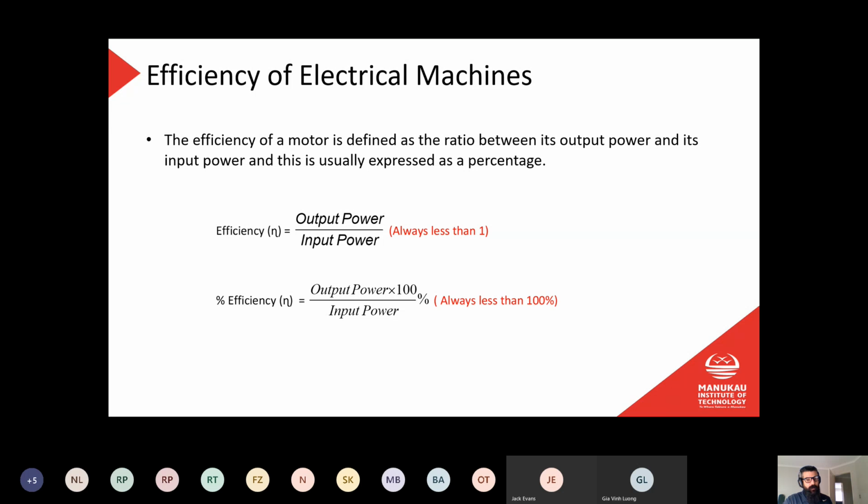On the outdoor unit we are evaporating a gas, so that the gas is at a low pressure. For a liquid to change state into a gas, it needs heat. So it draws heat from the outside air into that gas as the gas boils and evaporates, and then that gas moves into the indoor unit where we condense it.